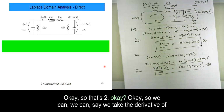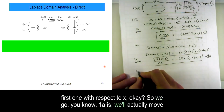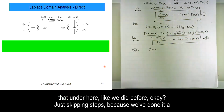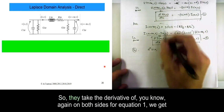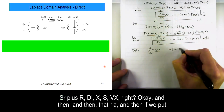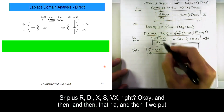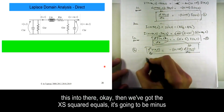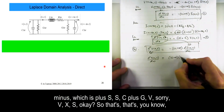Okay, so that's equation 2. We take the derivative of the first one with respect to x. We'll move that under here like we did before, skipping steps because we've done it a fair few times. So take the derivative on both sides for equation 1, we get the derivative of V equals minus (sL plus R) dI(x,s)/dx. Then if we put this into there, we've got d²V/dx² equals plus (sL plus R)(sC plus G) V(x,s).